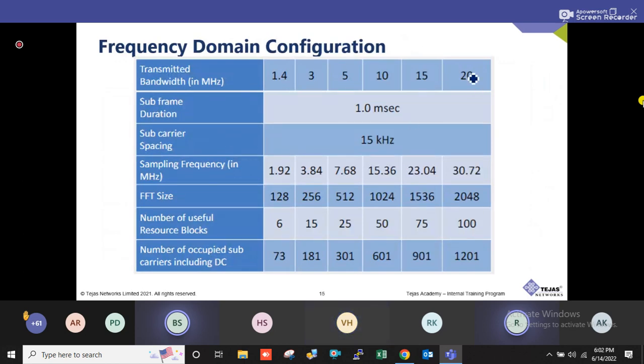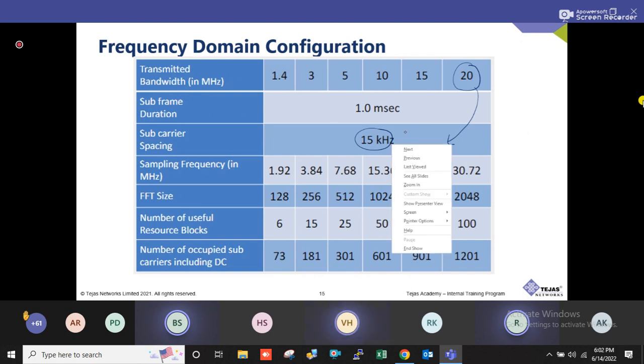See, you remember this. I have concentrated at 20 megahertz, which has a subcarrier spacing of 15 kilohertz for everything. Okay, this doesn't change. Now, 15 kilohertz. Please remember, I am explaining why it is 180 kilohertz. That's what I wanted to explain here, so that's why I'm jumping. So 15 kilohertz. How many 15 kilohertz are there in 20 megahertz? You can see here. How many are there?